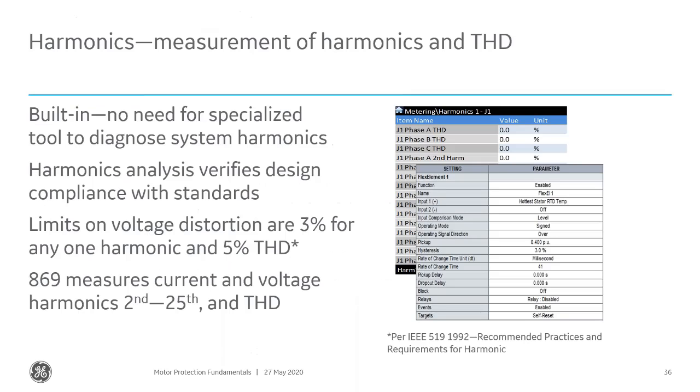Okay. So typically you don't operate from harmonics, right? I might not trip from harmonics, but I might want to alarm on harmonics. Now, harmonics can tell us certain things. They can help us diagnose problems inside the power system. So we can raise an alarm based on that harmonic content. If we've got a drive that's having a particular problem, or if the drive is injecting some noise onto our power system, we can look at the harmonic current or the harmonic voltage that's on our power system and raise an alarm for that.